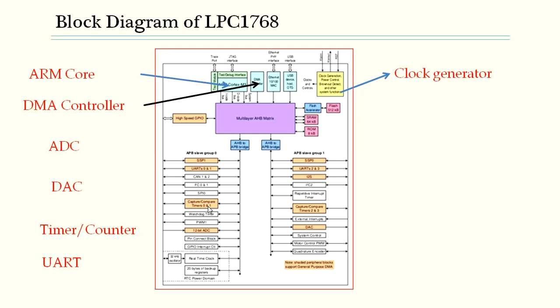The serial interface is also supported by the SPI, serial control. The SPI, that is the serial peripheral interface, is a full duplex serial interface designed to handle multiple masters and slaves connected to a given bus. Only a single master and single slave can communicate on the interface during a given data transfer. During a data transfer, the master always sends 8 to 16 bits of data to the slave, and the slave always sends 8 to 16 bits of data to the master.